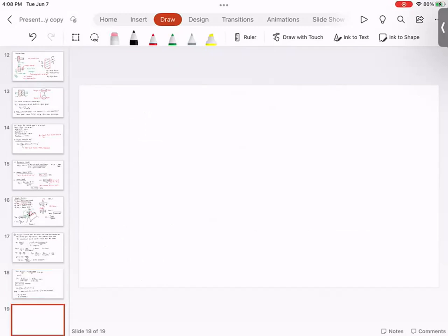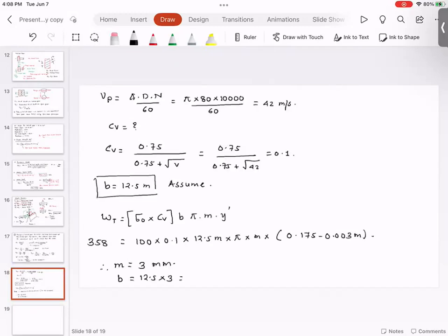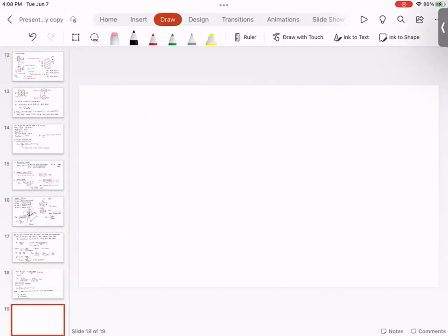Next step. So please note, in this problem, they are not asking us to check for the static stress. So I'm going to skip step number 2 and go to the checking for wear, because that is what is asked. Check gear for wear. And when I say gear, you always must check pinion. So velocity ratio is equal to 4. It's an external gear.